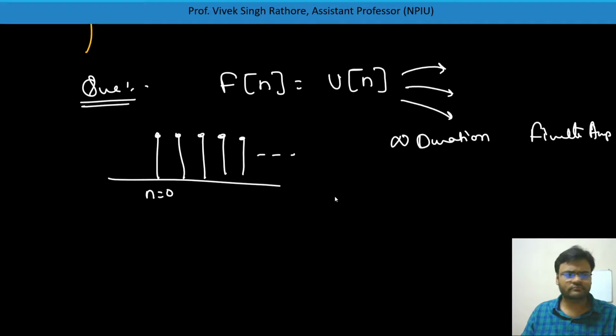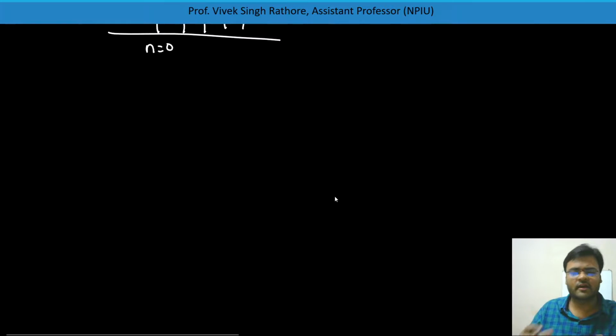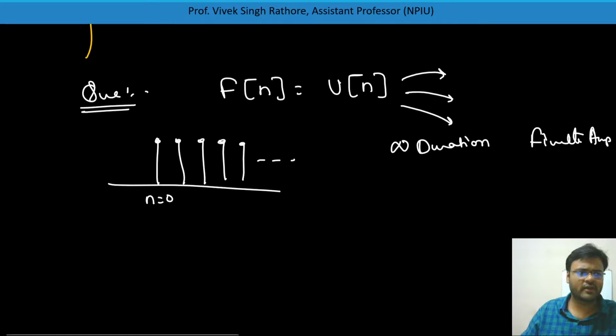If it is infinite duration and the value is not tending to 0, definitely it is not an energy signal, that is 100% sure. But we need to calculate power. If the power also comes out infinite, then we conclude that it is neither energy nor power. So first we will calculate power.